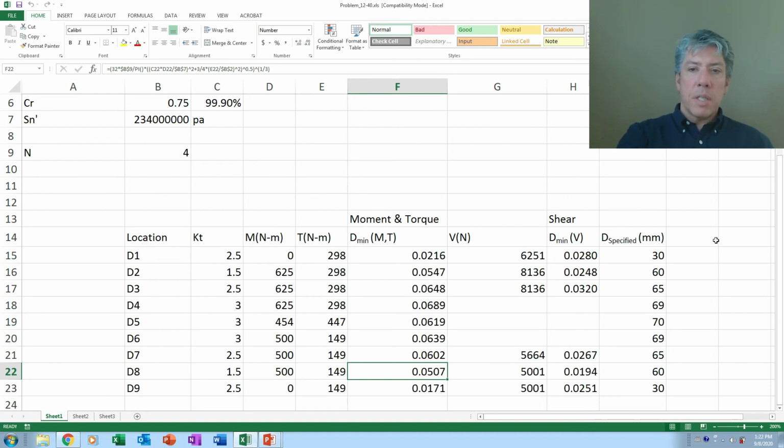And if I'm going up to 60 millimeters on one side anyway, I may as well make this shaft where it can be inserted either direction if that's possible. And that way, assembly is simplified and easier, and it's not like I've got a 1 millimeter difference that's hard to see and difficult to tell which way you should put the shaft in. No, it's just symmetrical. So that's the way I designed it.